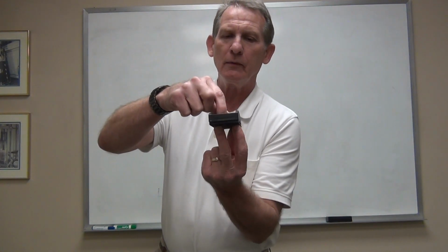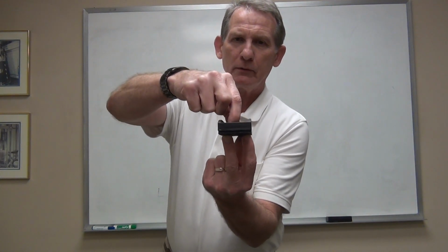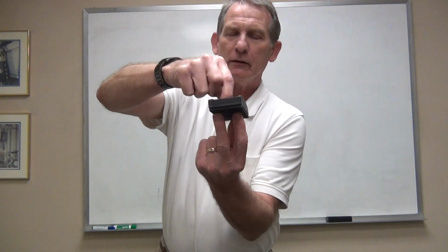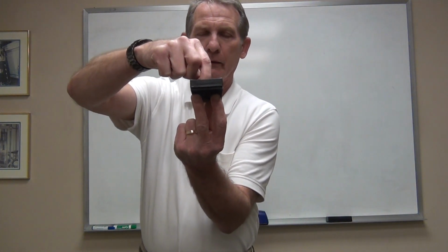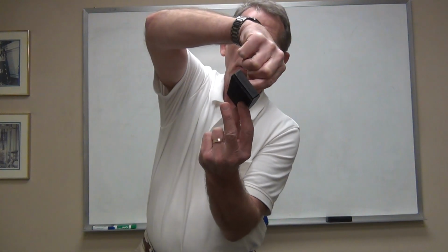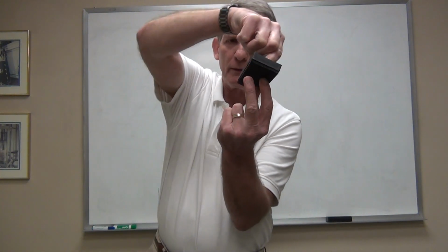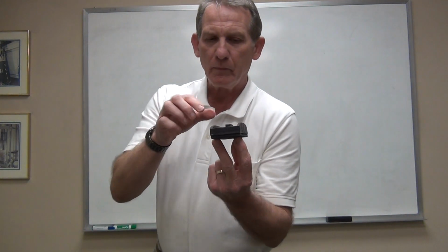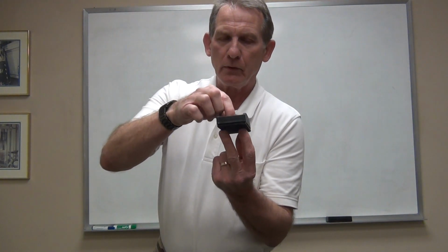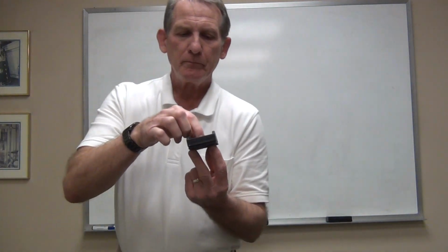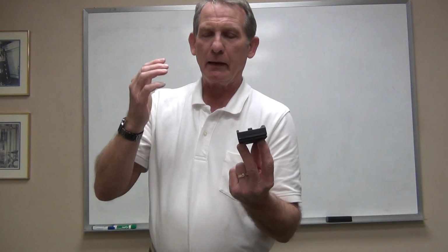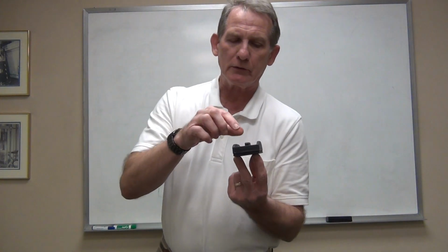Well, if my rule is that this component and this surface have to touch these 3 points, I have prevented it from doing this. Certainly it can't lift off the 3 points and still meet my requirements. It can't roll, otherwise it'll come off of that point. So I've constrained those degrees of freedom. Let's look at them in the groups that we put them in. We put them in translation groups and rotation groups.